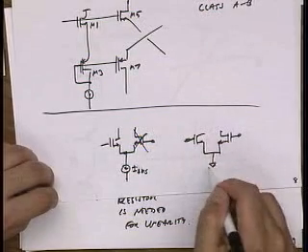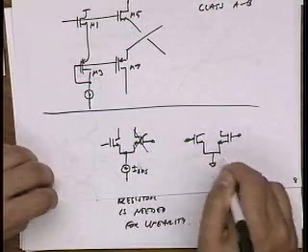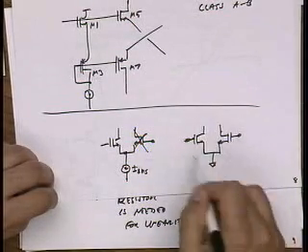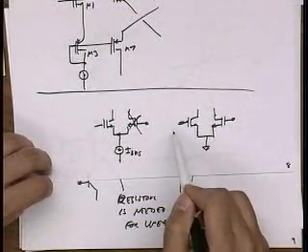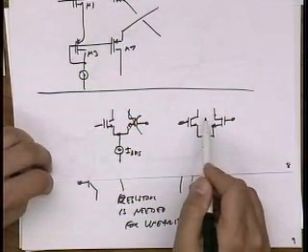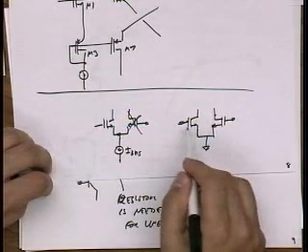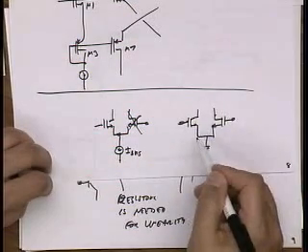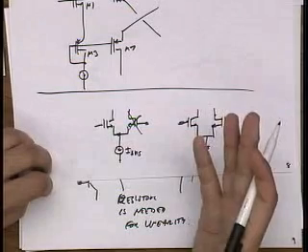So the reason we don't do that, as we discussed, is that it reduces our common mode rejection, right? Not having a current source here. Another potential problem with this approach is that there is a bias circuit that's on average forcing this current to be constant, right? And so if I apply a step input, I have to fight against that bias loop. And depending on the speed of that bias loop, it may actually limit the current if I slew too long.